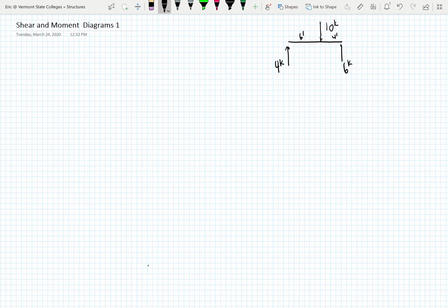You'll do that on your own. We're not going to make this part of the problem. The process we use is, the first thing we do is draw extended, light lines down from the key points: the supports and the loads. You'll see this makes drawing the shear and moment diagrams better. You'll use a ruler. I will get better as I go along. And this is where drawing things to scale really comes into play.